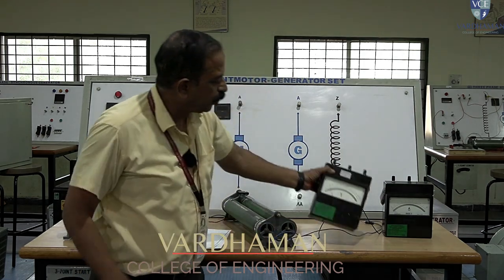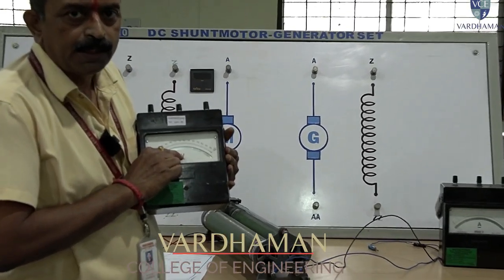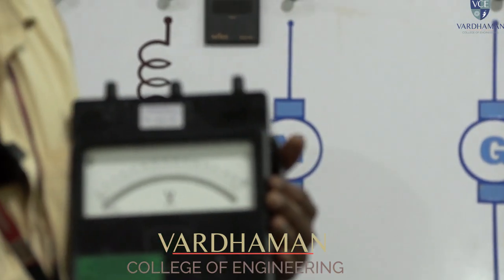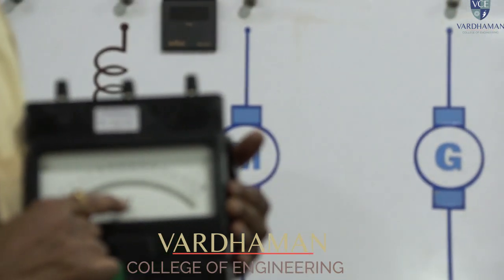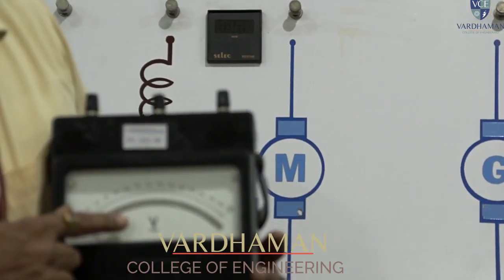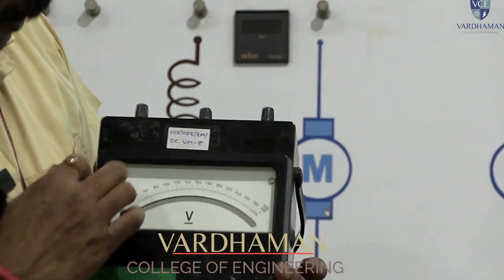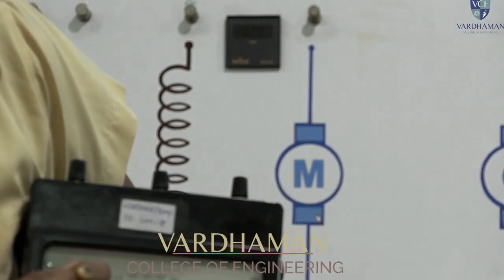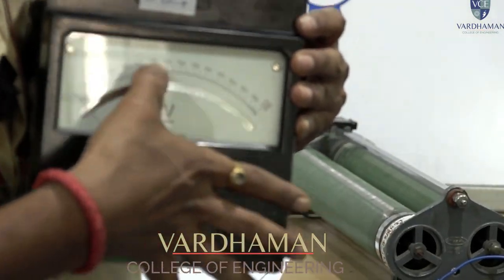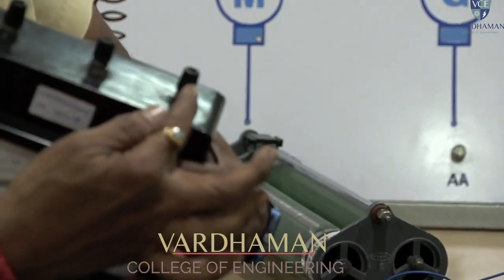And the voltmeter, which is given as this line indicates, is a moving coil instrument, which is used to measure DC voltages. Moving iron is for AC voltage, moving coil is for DC voltage. Since the generator is a DC generator, I have selected the voltmeter as a moving coil instrument which will measure the DC voltages, and the range of this meter, you can see, is 600 volts and 300 volts. The dial belongs to 300 volts, and you have separate voltage terminals for 600 as well as 300.